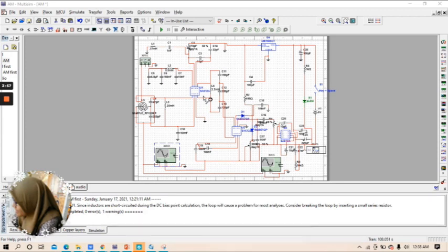Inside this IC, the signal is mixed with the modulating frequency, which is the intermediate frequency. The output is fed into one IC, which has a reception bandwidth from 150 kHz to 3 MHz.